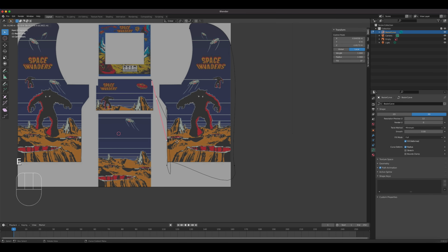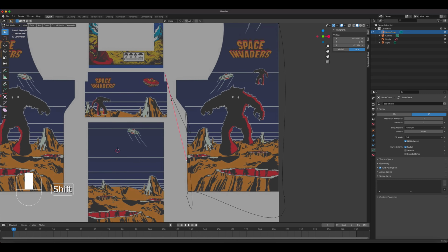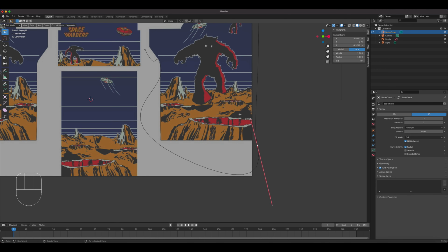Let me start fixing my Bezier here so they're not too off. I kept pressing the wrong button. Make sure you don't want your curve to be going the other way. So how do we get corners right here? It's actually pretty easy. Select your point and then press S and then 0, so you're basically zeroing out the handles. S to scale, press 0 and Enter.